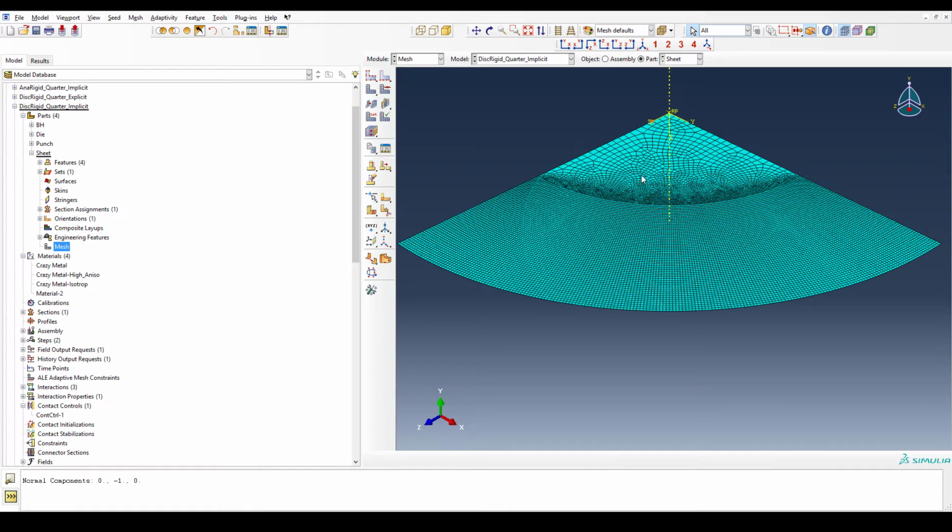Why did I choose this kind of meshing? Because the radius of the punch will be somewhere here, in that swept area that behaves axisymmetrically. I really encourage you to perform a simulation with such a mesh, and one without using the sweep option, which consists of a mesh entirely like the inner radius.